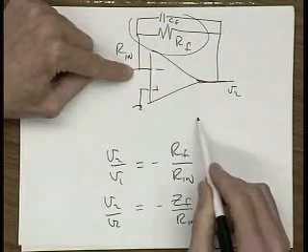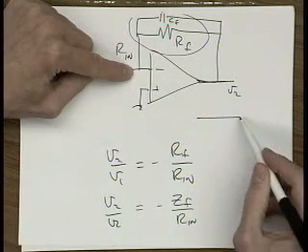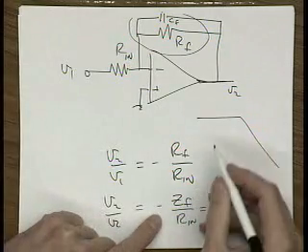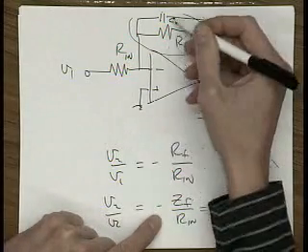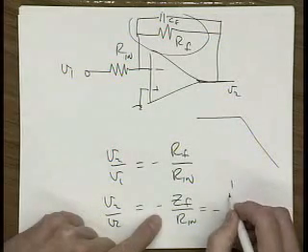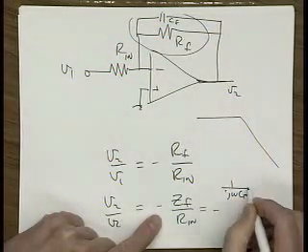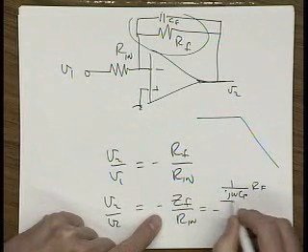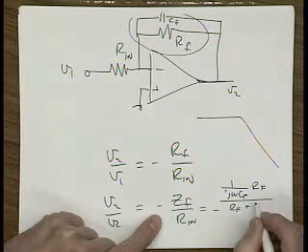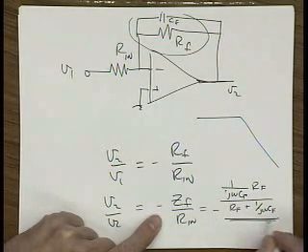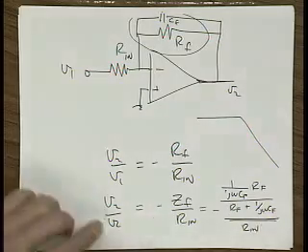So what does that mean? What's going to happen? At high frequency, this thing is going to fall off. Well, let's just plug in the numbers here. ZF is really the parallel combination of CF and RF, right? So that's 1 over j omega CF, I'll use j omega instead of s this time, times RF over RF plus 1 over j omega CF, okay, all over Rn.